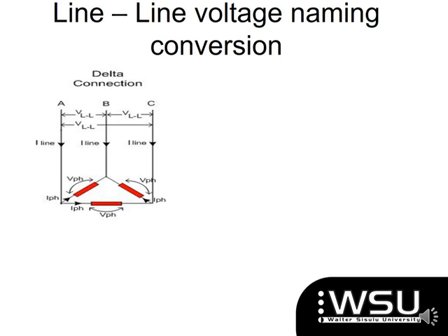So I'm going to start with the delta connection. You can see there's a triangle at the bottom and we're going to go there to name these voltages. For your V line to line, or what we just call a line voltage, it is the following. Between phase A and B, in a clockwise direction, such as the thick black arrow I've just put, clockwise.